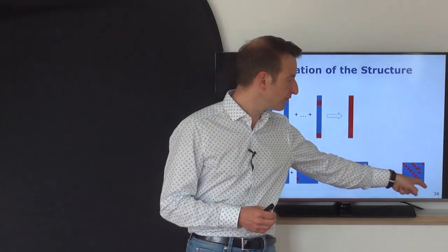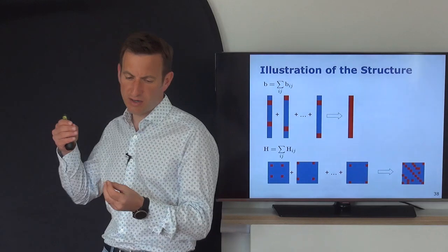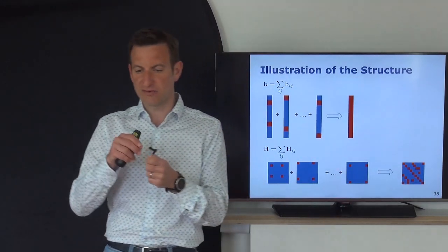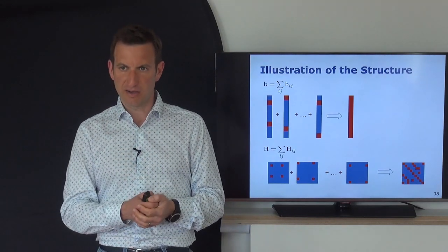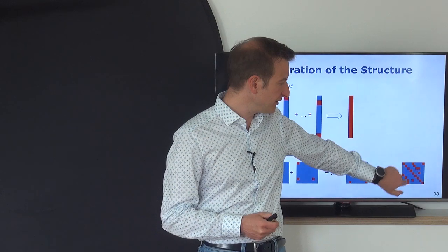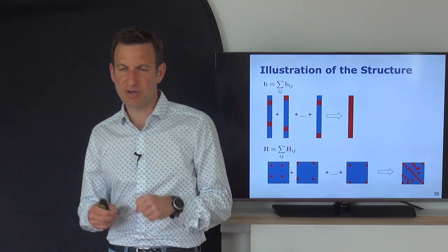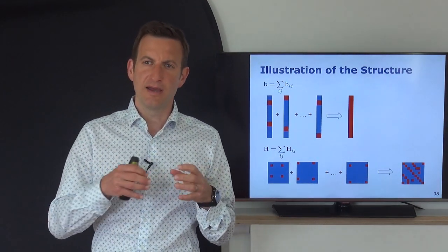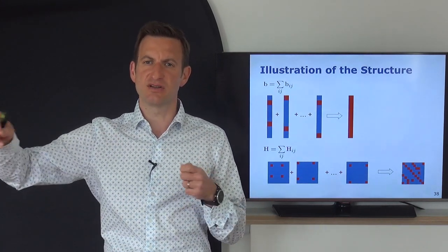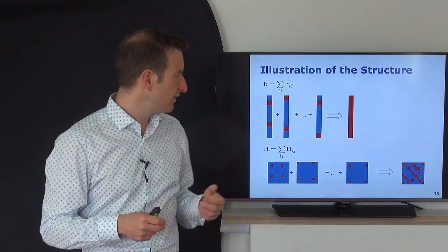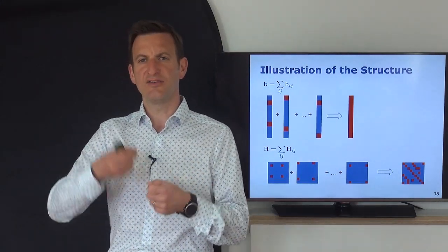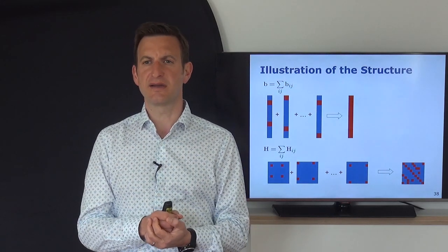So I have direct constraints here on the diagonal, and also the direct off-diagonal blocks, because it relates how the current pose and next pose are connected with each other. And I have a couple of elements in the off-diagonal, which are basically my loop closure constraints, where a node xi is connected to a node xj, which are not sequential. And so this matrix can be seen as kind of an adjacency matrix of that graph, which tells you what the connections in your graph actually are.